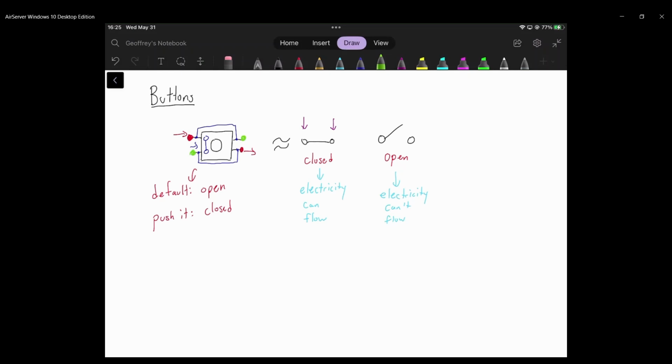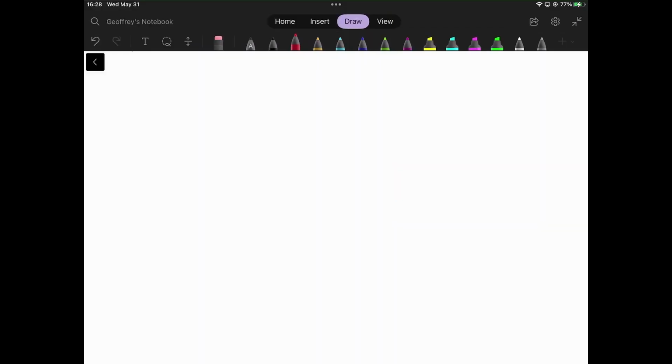If you connect red with green, you'll get a short circuit. And that's not what you want, unless you know what you're doing. But in any case, you want to connect red to red or green to green with push buttons. Well, that's all well and good, but how do you make a circuit for that in Arduino? You can't just attach a push button into the sockets for an Arduino and expect it to work. That's not how this works.